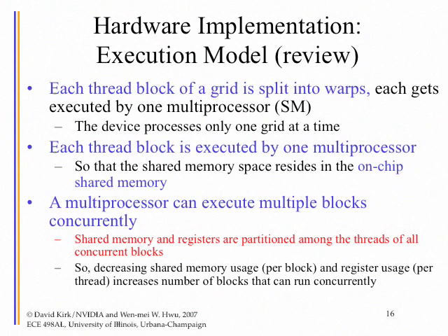The hardware is going to reduce the number of threads running on the processor until it fits. But the granularity of reduction is going to be on a block basis. So rather than just reducing enough threads to fit into the registers, you will take out one of the blocks. So now you're going down from 3 to 2. And that means you're going to have 512 threads rather than 768 threads. You immediately take off hundreds of threads when this happens.